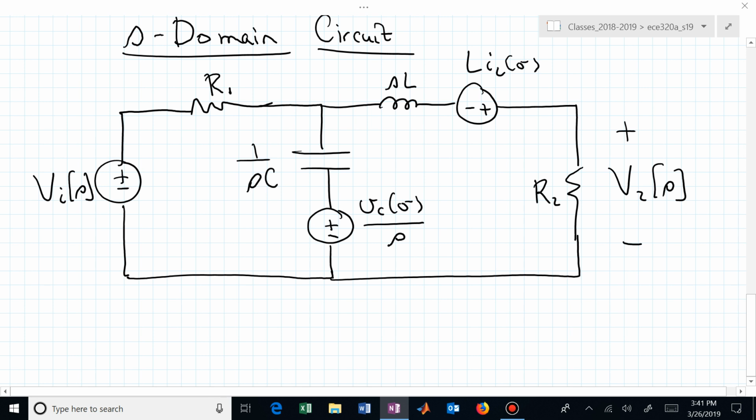If we were doing nodal analysis, then we would be putting current sources in parallel with the capacitor and the inductor. But in this particular circuit, I've deliberately introduced a voltage source so that I still have not introduced another mesh in this particular circuit. I still have two meshes that I will perform the analysis with.